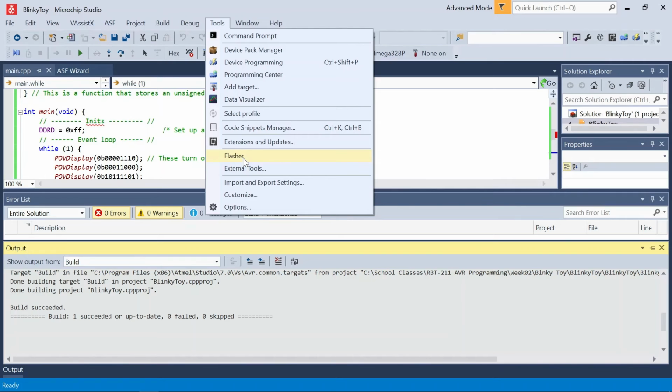To get around this, before you flash it, take those wires off. So pins 0 and 1 should be out of the board, okay? Flash it and then connect those wires and everything's going to run fine. If you try to get around that, it's not going to work. And this is just from hard knock experience, okay? So that's pretty much that.